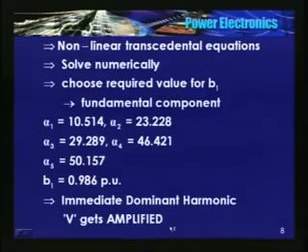But then again, the frequency of the 17th harmonic may be higher, and it gets filtered out by the machine inductance. Whatever I have told in my last lecture holds good. But this is the disadvantage of the harmonic elimination technique. It's quite attractive because you can try to optimize certain performance indices of a machine.